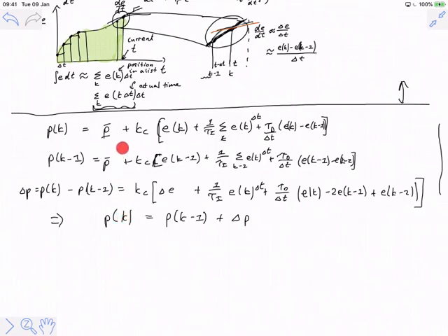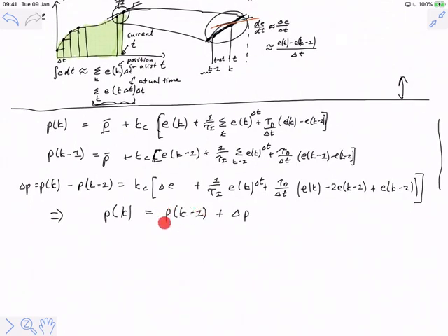I will calculate exactly the same running sum of this integral. Does that make sense? Because I'm doing all exactly the same calculations. And now a lot of you are looking puzzled because, but wait a minute, the book says velocity form controllers do not exhibit integral wind-up. This only is true if I read the previous output back from whatever I used to make that output move.